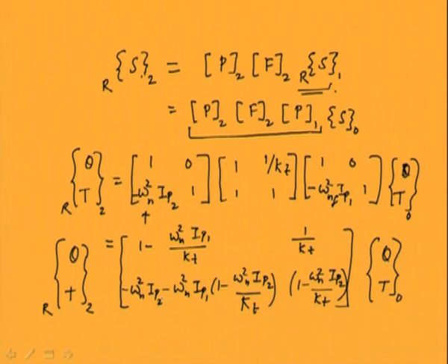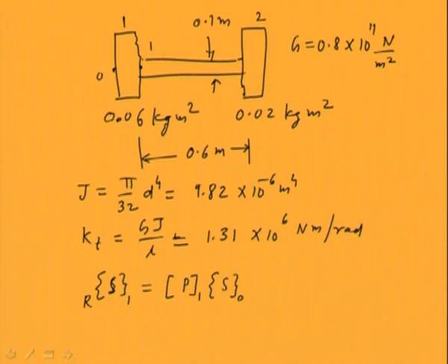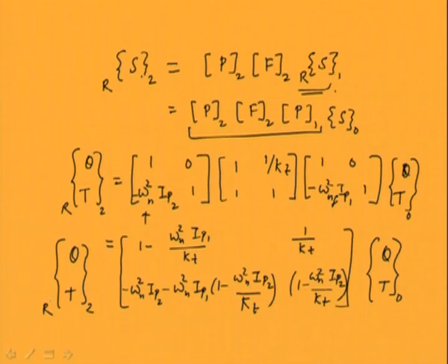So boundary conditions is, because if we go back to the previous thing, this rotor is also supported on frictionless supports. So both the ends are free for this case also. So there is no torque at 0 station and there is no torque at this second disk right side. So both torques are 0, but displacements are not 0.